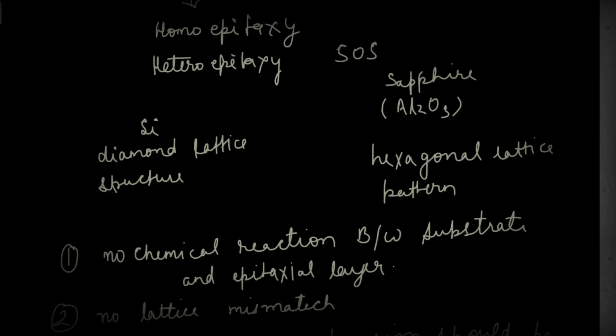So the three cardinal rules for the heteroepitaxial process: no chemical reaction between substrate and epitaxial layer, no lattice mismatch, and the coefficient of thermal expansion should be matched.